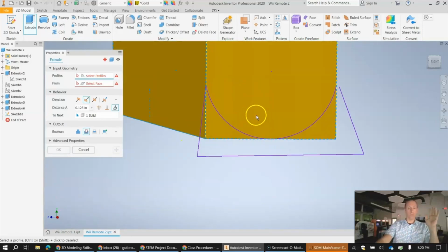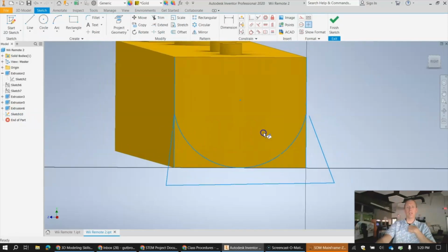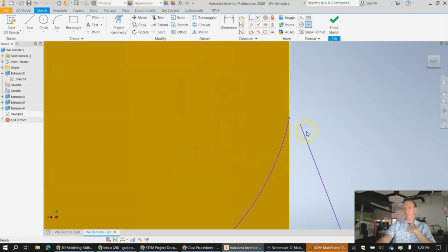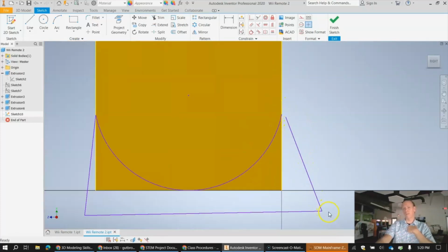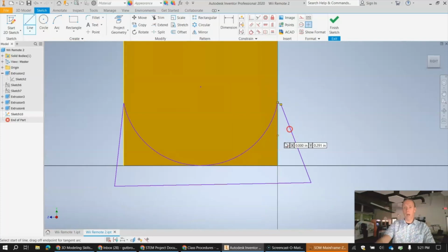So, okay, let's fix this. I click cancel. I'm going to go back to my sketch 10 by double left clicking it. We're going to edit this sketch. We're going to close this baby up. So I could close it just by adding in another line here, or I could delete this if I really wanted it and just draw another line. The simple thing to do for me right now, I'm just going to click the line tool. I'm going to click here. I'm going to close that like it's locking in. Boom, boom. So right now, I have a fully closed shape. You do the same.